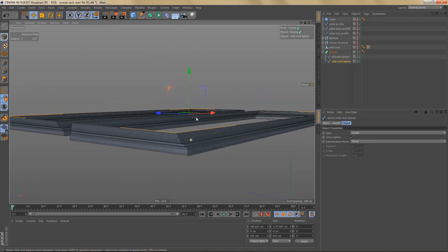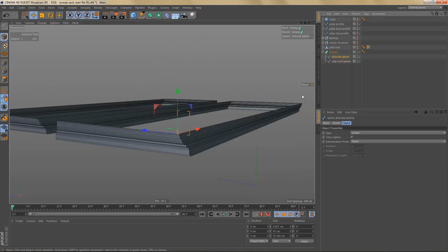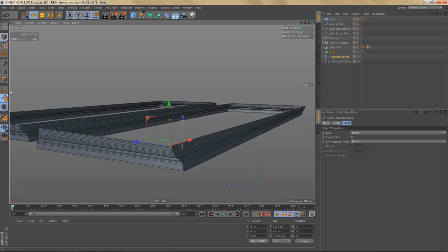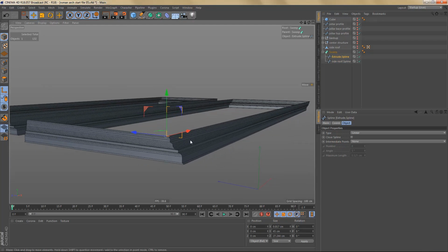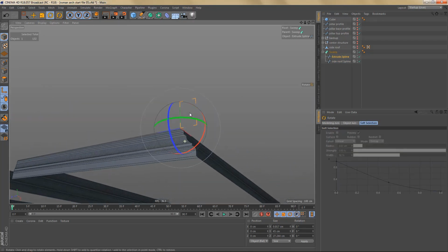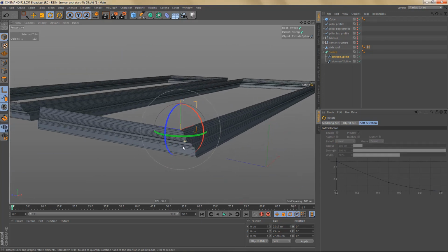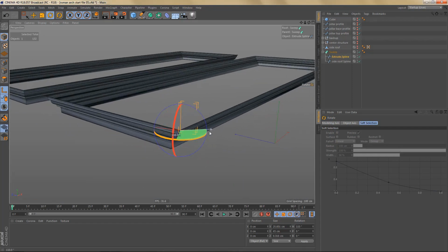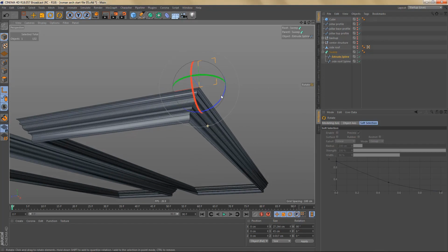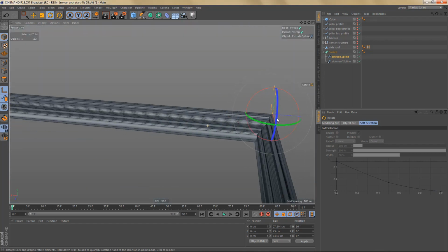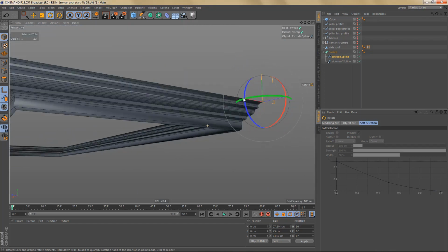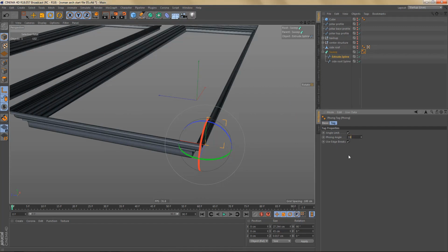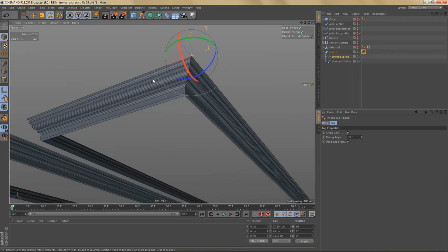And you can see this doesn't look right, so we need again to rotate the object axis of our profile spline. Make sure you're in model mode, switch on enable axis and grab the rotate tool. And I honestly never can tell which way to rotate these splines. I'm going to try and do 90 degrees this way, and actually this looks like that's all we need to do here. Let's go ahead and change the Phong angle to 33.